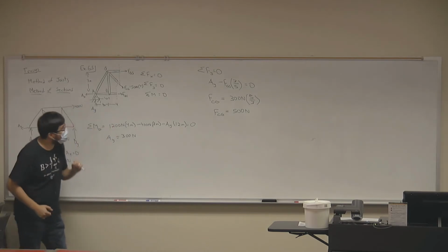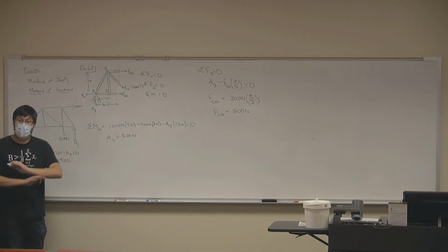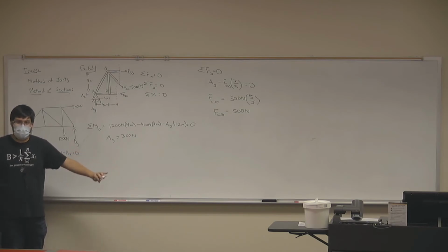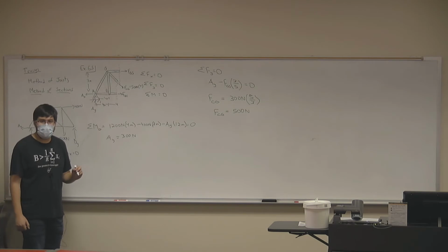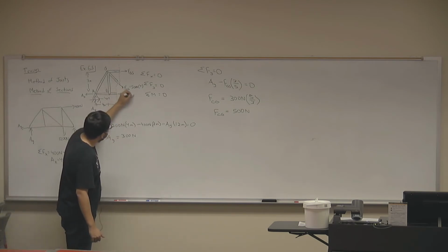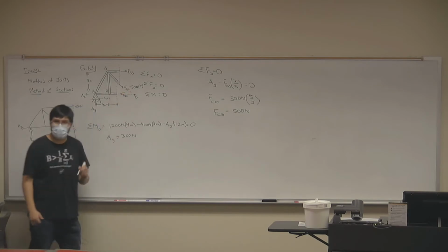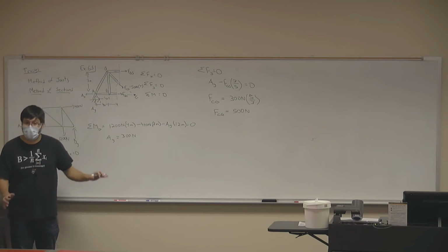I would always try to pick equations that I can just solve without having to go back to additional calculations. So Lorenzo, here's a suggestion. Sum of moments equals 0 at any point. That doesn't mean that it has to be a point in my body. What if I choose point C as my point? Doesn't matter where you take that point.